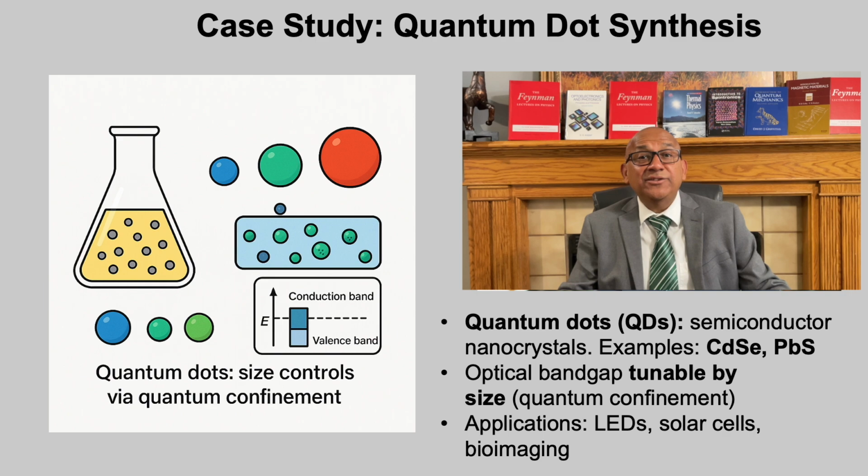As the crystal size decreases, the band gap widens, shifting emission toward the blue. Larger dots emit toward the red. This tunability makes quantum dots extremely attractive for applications ranging from quantum dot displays and LEDs to solar energy harvesting to fluorescent markers in biological imaging.